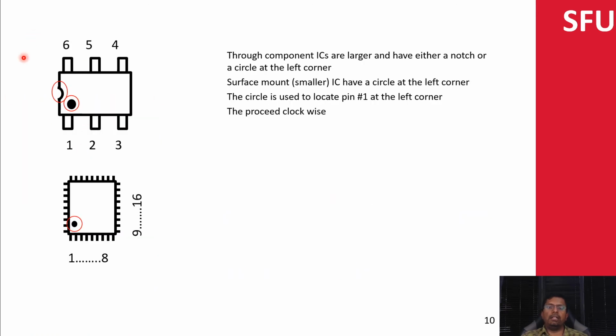Typically your data sheet will give you pin numbers and what you need to connect to them. Here there is typically a dot on the integrated circuit, and for the dual inline pin you also have a small notch, and you place it as shown in the figure. You can start counting, and this pin is labeled number 1, then 2, 3, 4, 5, 6. So you go counterclockwise.